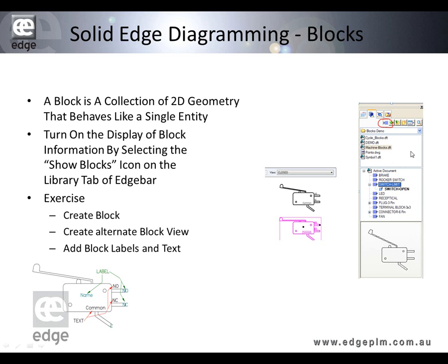Blocks are similar to AutoCAD blocks, if you like, and we can use AutoCAD blocks on the fly. But what we'll see over here is a drawing sheet that contains a library of blocks, and any that we've got open currently we can pick the blocks from. And you can see the active document here. It's the machine blocks we have open. It's highlighted, and we have a list of blocks in here that we can access.